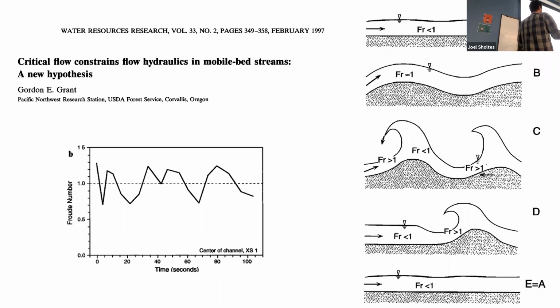We start to get really supercritical flow conditions, waves, hydraulic jumps, and then everything washes out as this water accelerates and moves fast enough. And so that washout is then this kind of release of water. The bed becomes smoother, and then we get this surge of water that washes downstream. So it's actually a phenomenon that happens on its own through the interaction of flow and moving sediment and developing and moving that bed.